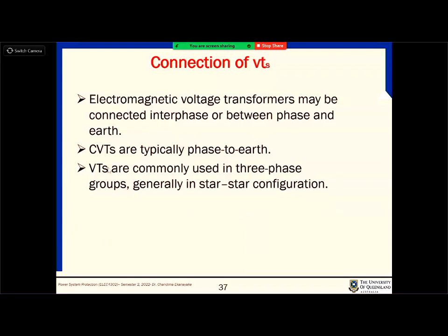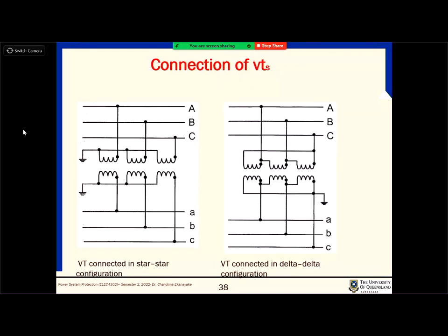And then on the secondary side also, they are grouped, as on the primary side. We usually deal with not single phase but 3 phase, and secondaries are also grouped in different ways, like this. As an example here, the secondary connection is a Y connection. And it can be a delta connection as well. But you can see that even in the delta, you have a ground connection.